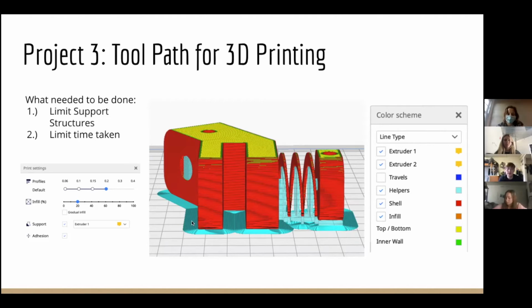So one of the main things that we did when designing the toolpath was ensure that these two holes that you can see in red were on top, because if they were oriented on the bottom, there would need to be more support structures through them holding them up, which would be more filament and be difficult to remove and could cause other issues.